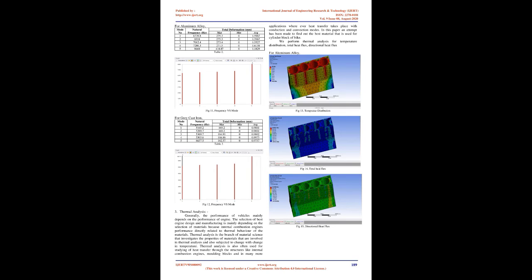the component is not subjected to any external loading or vibrations; these are called natural frequencies. Modes of vibration: the component will deform in different directions at corresponding different frequencies. These different directions of deformation are known as modes of vibration. The natural frequencies and the modes of vibration constitute the characteristic solutions. In modal analysis we find out the values of natural frequencies and modes of vibration.